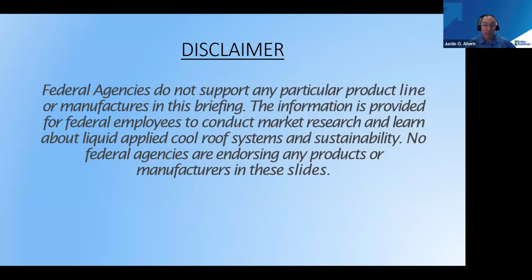The energy cost savings, it's a third less construction cost on average, meets California emissions. Warranties that work, an NDL option, manufacturer inspection, and certified installers. Seamless liquid applied systems are monolithic, so there are no seams to fail, which, with penetrations and seams, seem to be the most water intrusion susceptible points of a roof. This avoids that completely. It reduces the heat island effect, the energy cost savings, less air handling unit cycle times, less CO2 emissions is what that means, less electricity use.